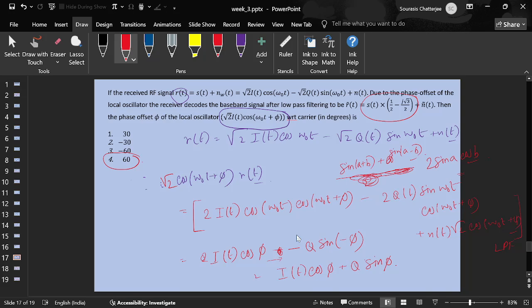In the context of wireless, you will see more the pass band term because when you move your baseband signal that is centered around zero frequency to some high frequency, that creates a certain band, that's why we call it pass band. So essentially they are same only. What statement I made earlier that they are different, it's wrong actually. They are same.